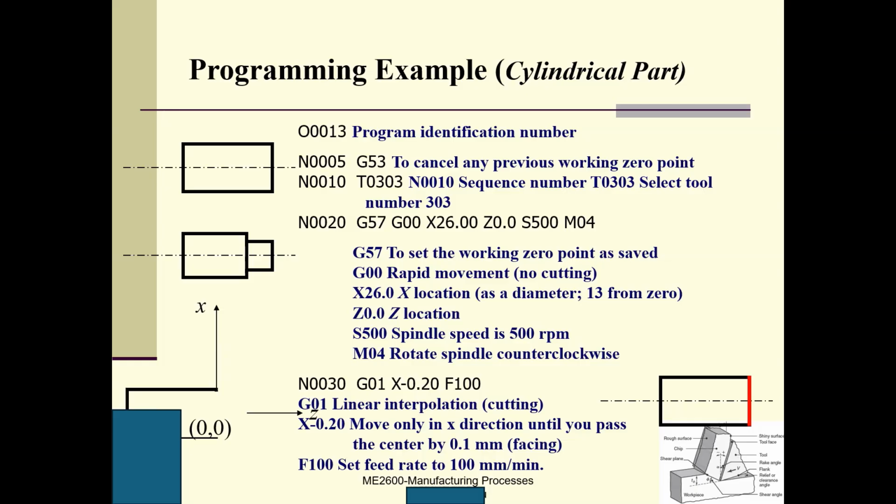The CAD we do the model, and the CAM output is a G code and M code. The CAM is a library, okay? So they convert specific instructions to the general standardized G code and M code. This is what CAM, computer aided manufacturing, does. That's a very good question.